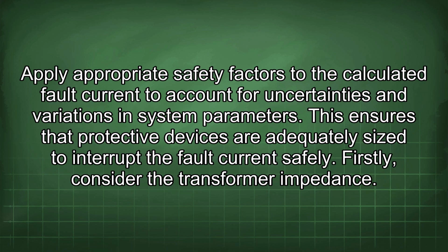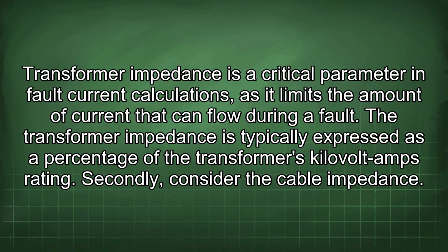Firstly, consider the transformer impedance. Transformer impedance is a critical parameter in fault current calculations, as it limits the amount of current that can flow during a fault. The transformer impedance is typically expressed as a percentage of the transformer's kilovolt amps rating.